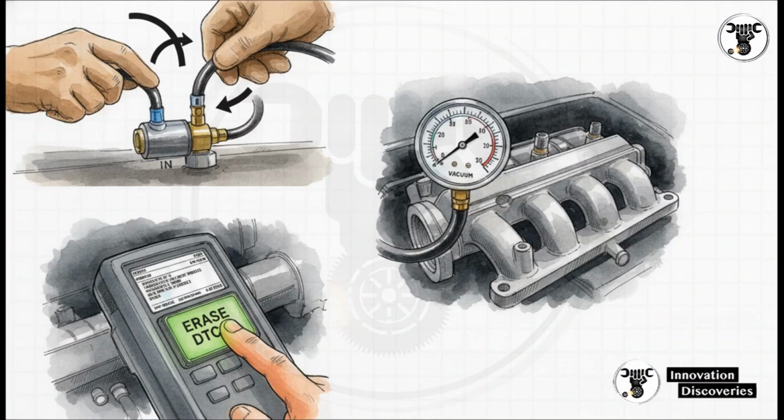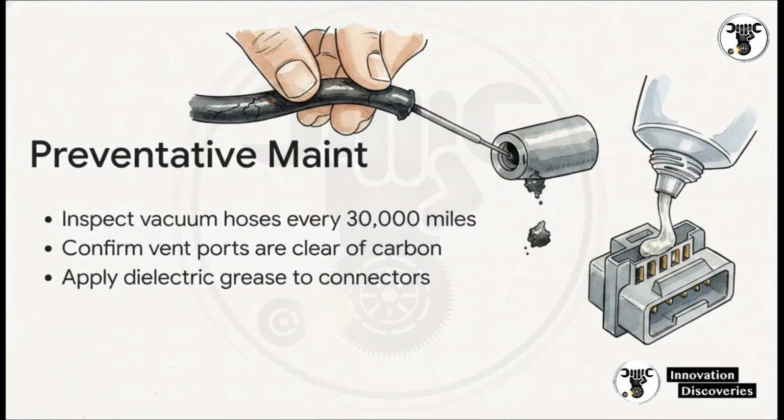Always label your hoses. Second, ensure proper torque and secure bracket mounting during reassembly. Excess vibration is a known solenoid killer. Third, verify your intake manifold vacuum source. Make sure you actually have that 10 to 18 inches of mercury reaching the solenoid in the first place. And lastly, never forget to clear those historical DTCs and verify the repair with the scan tool on a test drive. For those of you managing commercial high-mileage fleets, you really need to standardize a preventative maintenance and data logging schedule. Documenting these performance metrics helps track solenoid health across the entire fleet before codes even trigger.